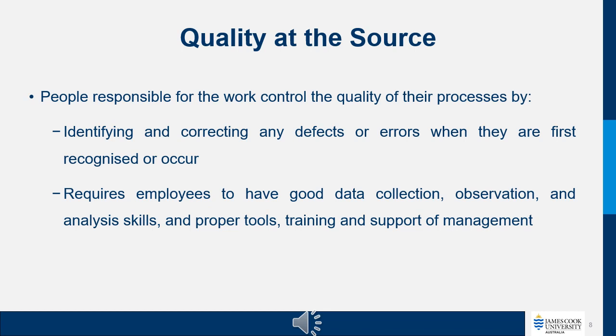To effectively implement quality at the source, employees need to possess good data collection, observation, and analytic skills. They should be trained in identifying deviations from the desired quality standard and have the necessary tools and resources to address these issues. Proper support from management is also crucial to provide guidance, encouragement, and a culture that values quality.